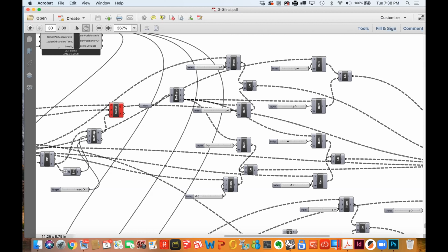That's the beauty of the computation, and how it complements the fabrication process so well. You have that feedback loop of, okay, we've laid this facade out by a 4x8 sheet, but 4x8 isn't the most optimal way, and I have 1,000 unique shapes. Well, I can just tweak one variable and it will update, and now I can start cutting a 30-inch wide sheet. And it's so easy to quickly tweak these variables and get a faster optimized fabrication process.